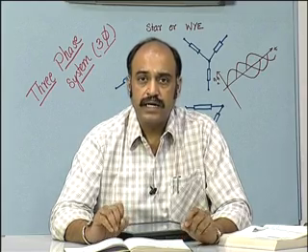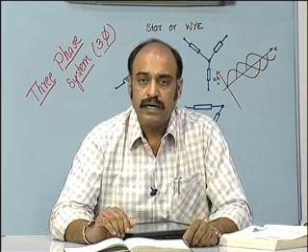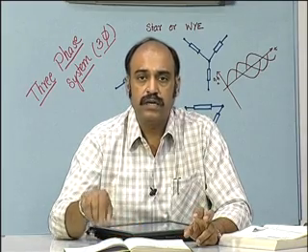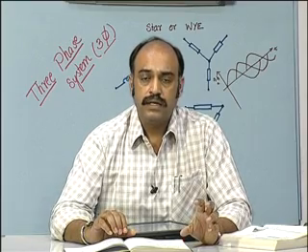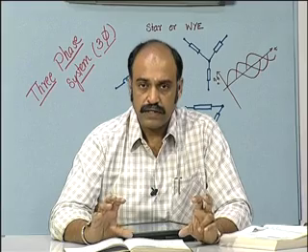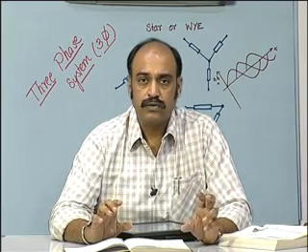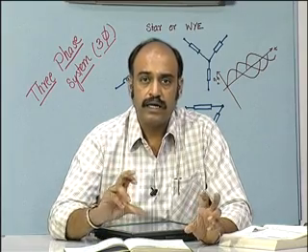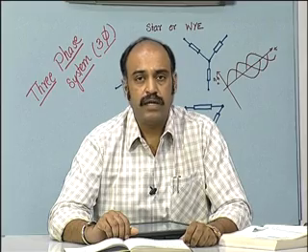In the case of the delta, there is no concept of a neutral point. The 3-phase circuits are connected sequentially one after the other in the form of a ring, and the 3 vertices of the triangle are directly connected to the 3 terminals of the source.